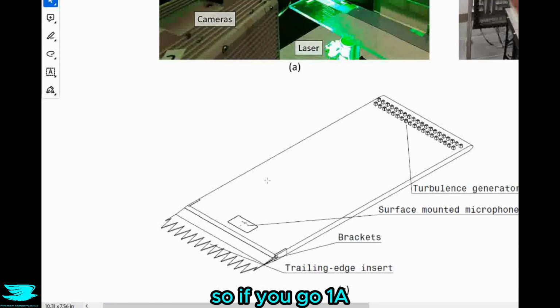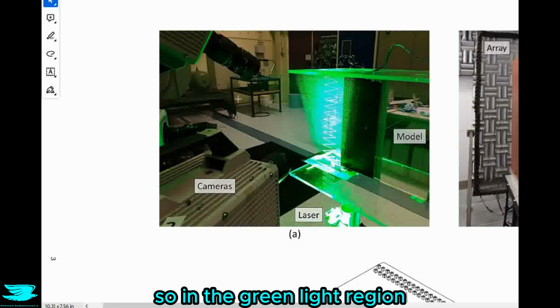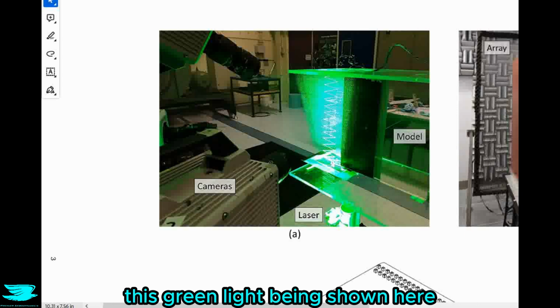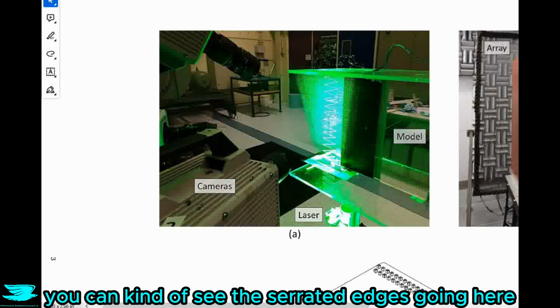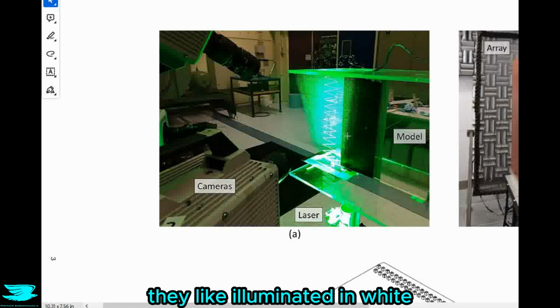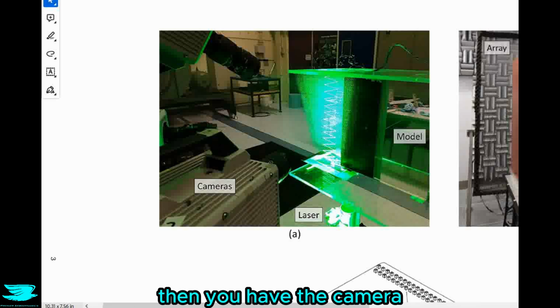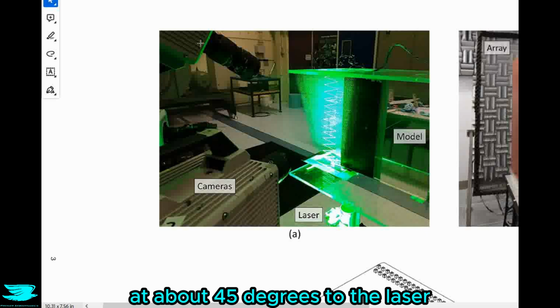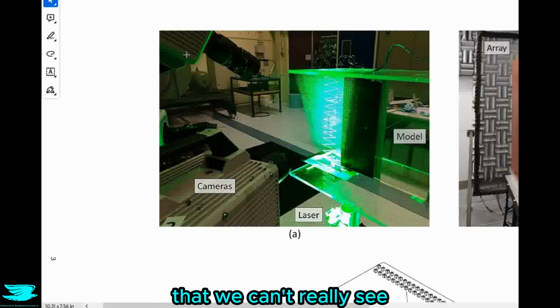So in figure 1a, we see the general angle of the PIV setup. In the green light region, this green light being shown here, is a laser sheet shining straight through. You can kind of see the serrated edges going here, illuminated in white. I guess that's a reflection kind of thing. Then you have the camera at about 45 degrees to the laser. I guess there might be another camera or a couple of cameras behind this that we can't really see.